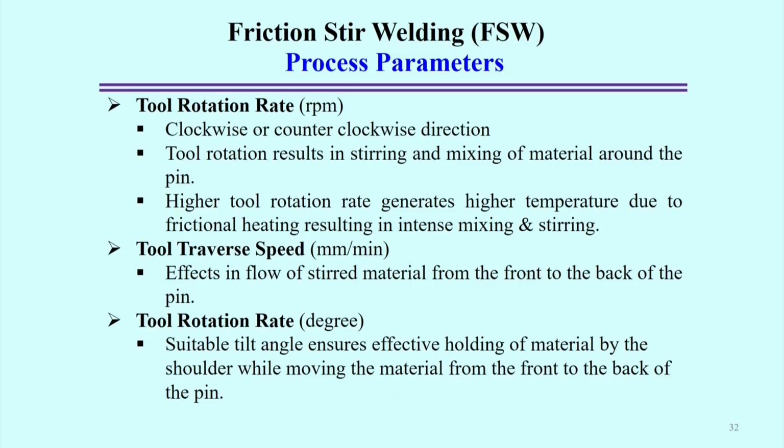The tool can be moved in a clockwise or anti-clockwise direction, and this tool rotation results in the stirring and mixing of the material, mainly around the tool pin. Therefore, if the tool rotational speed is very high, normally heat generation will be more, because at high rotational speed the frictional heat generation will be more, and that creates intense mixing and stirring of the material.